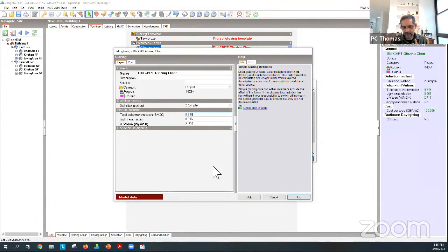coefficient, which is how much solar radiation is coming through that window. So you need to think about, okay, is this building only occupied in the day? Is it occupied 24 hours? In that case, what should my window be doing? What kind of shading should I be providing? That sort of thing, okay?